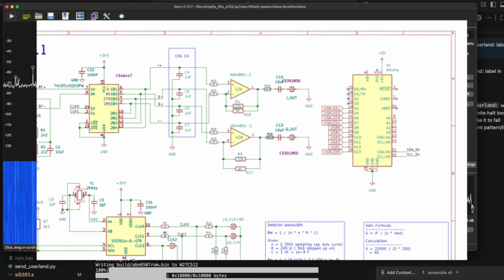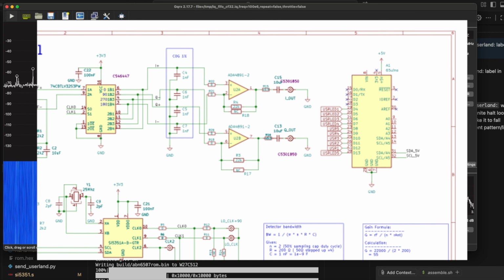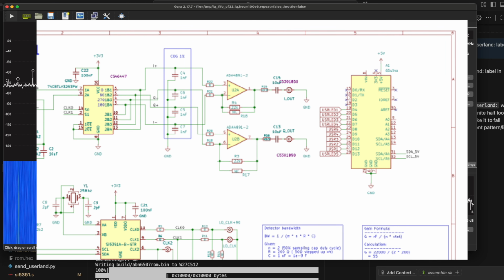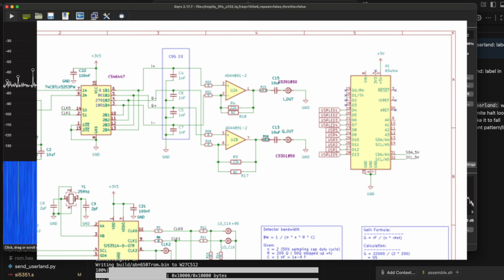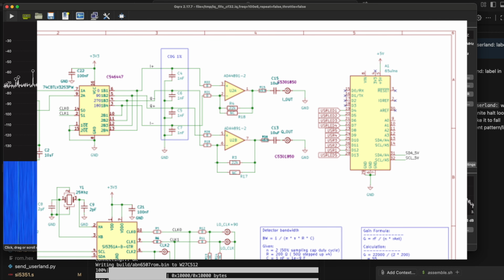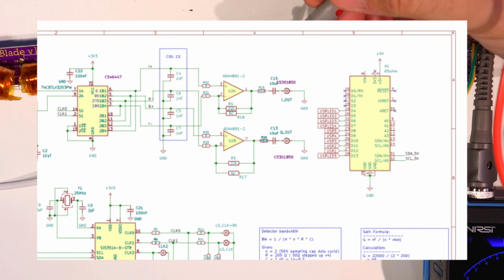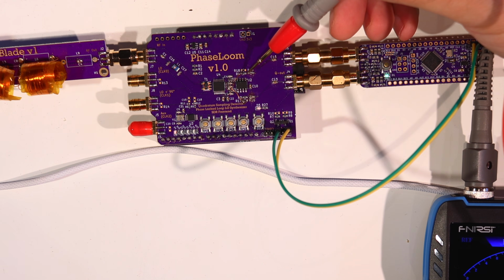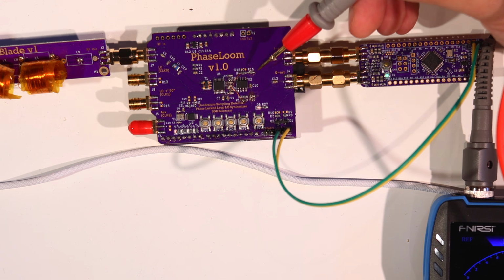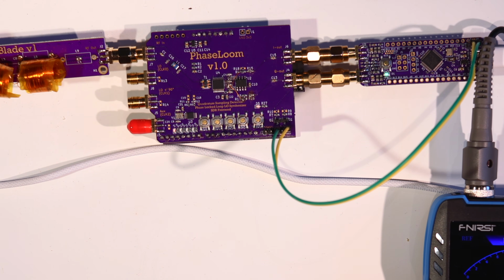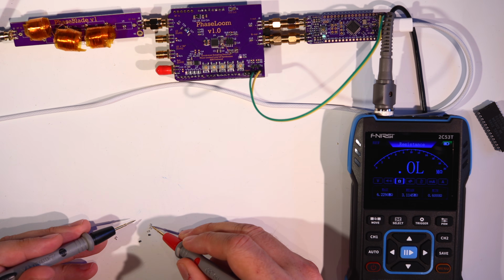have. But luckily, we don't need all the resistors I have to be precisely the same value. We just need two that are close to each other. They don't even have to be very accurate, since we don't care if they're exactly 47,000 ohms, as long as they match each other very precisely. Which is why this little procedure I'm doing is called matching.